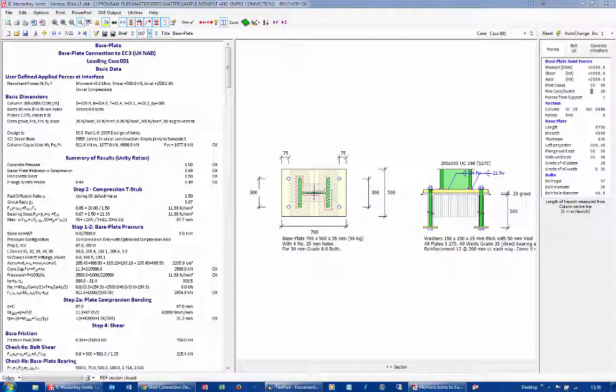The first thing is we design using a T-stub, very similar to the Eaves and Apex. And this T-stub means that for the plates, the steel, we can actually get a better design because we're using all those yield line patterns in, I believe, double curvature bending. But where we fail is in the concrete strength. Yes, we're using FCD and it's times its normal alpha over gamma C, which gives us an 11.33 Newton per millimeter squared capacity. But we then have the bearing stress, which is FJD times BJ.